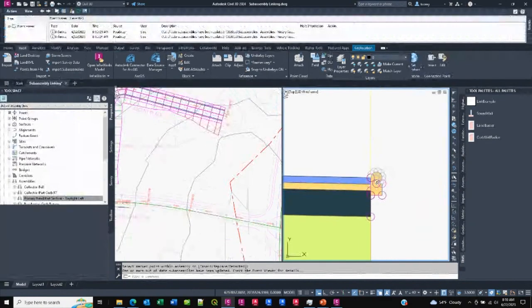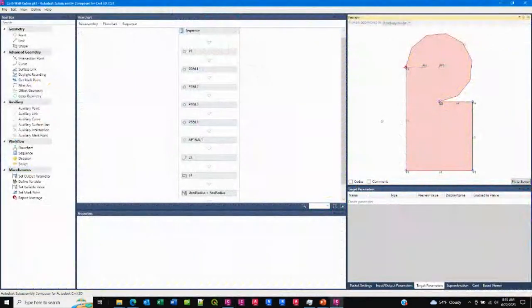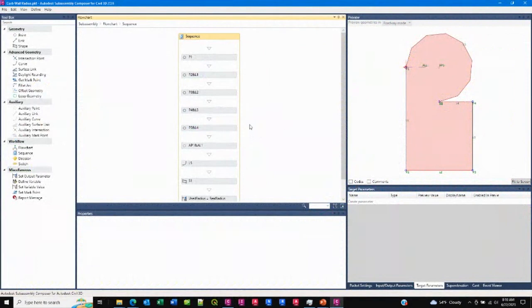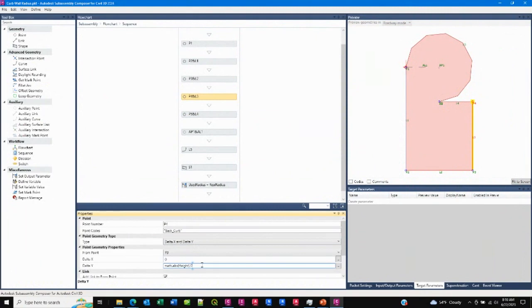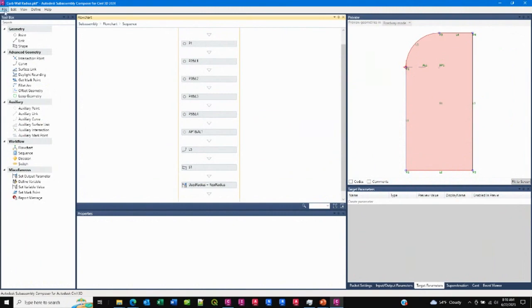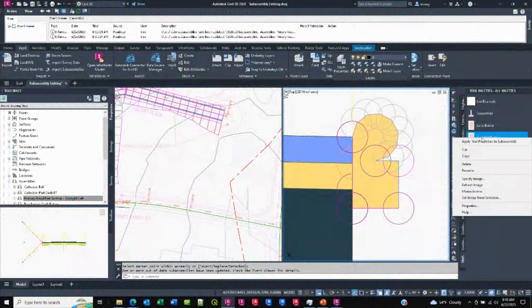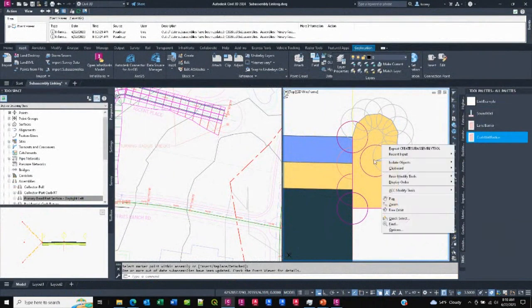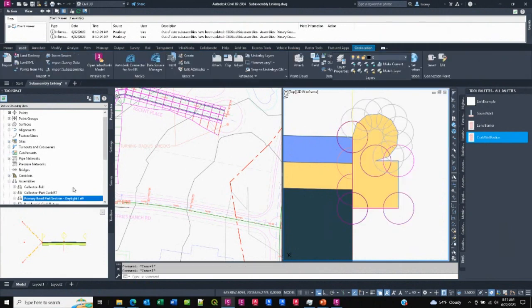Okay, so I get that messed up look like you see over here in my subassembly composer. So let's say I fix that. Get rid of the divided by 2. So that looks right. So now I save this. Back over in Civil 3D, I just tell it to refresh. Whoops. Pick this subassembly, tell it to refresh it. Guess it's not on there, it's only out here.